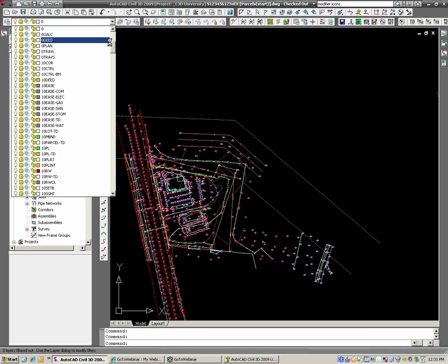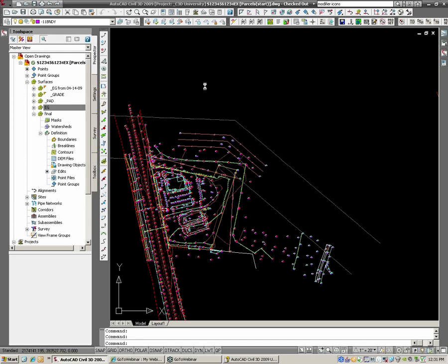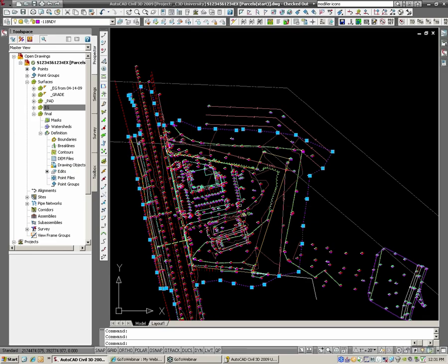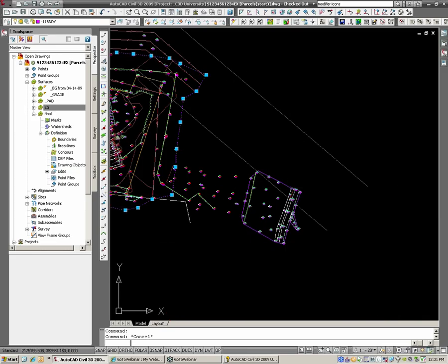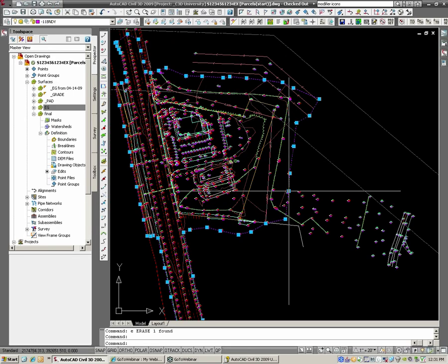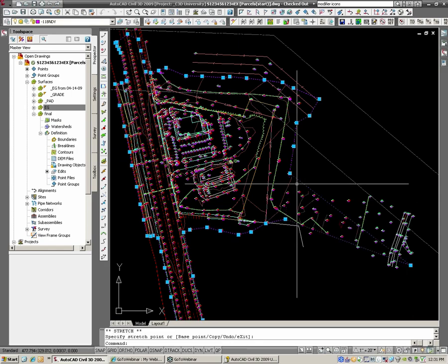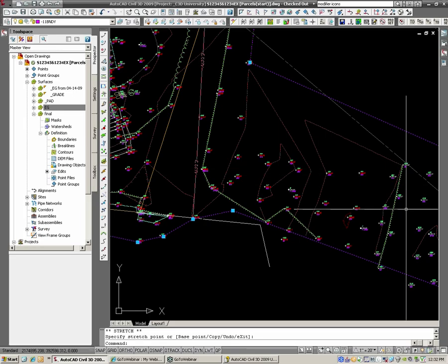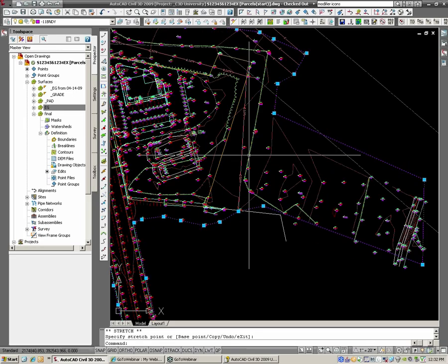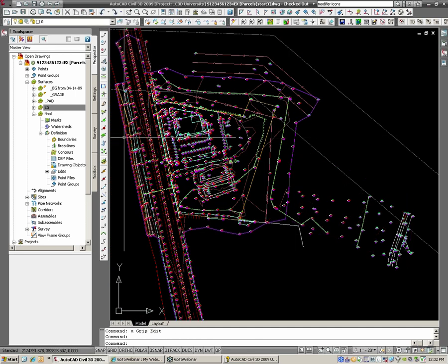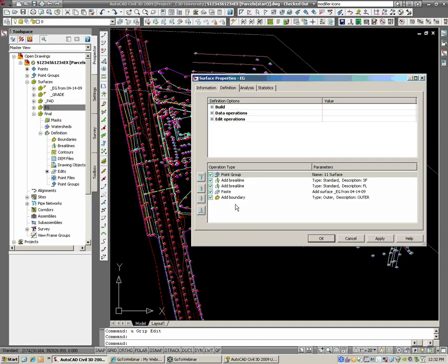Well, why would that disappear? Because my boundary for this surface is here. So it reads the triangulation from this surface I created over here, brings it in, but then it trims it out because my boundary's on this side. If I grab this boundary and slide it out, you'll see it start to reappear, but I'm also going to get the span in between here because these are points a part of this larger surface, as we did last time. So the order of your boundary and whatnot is important.